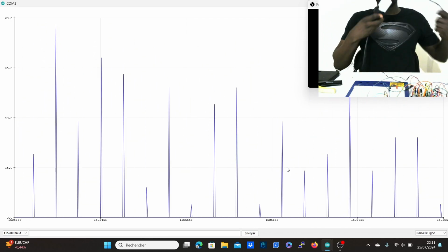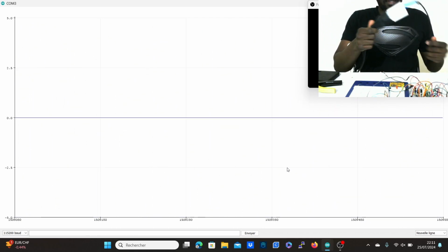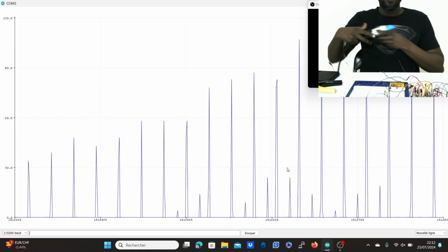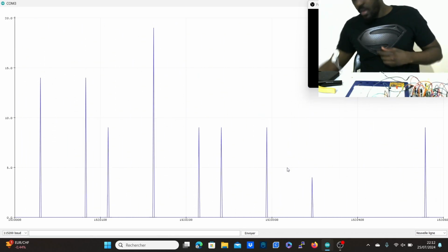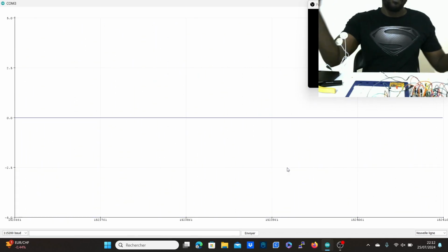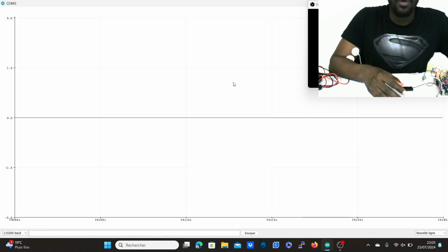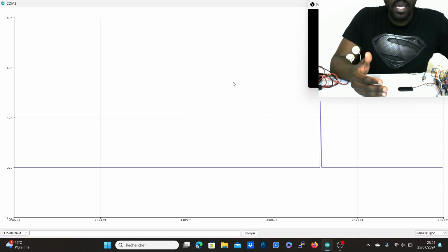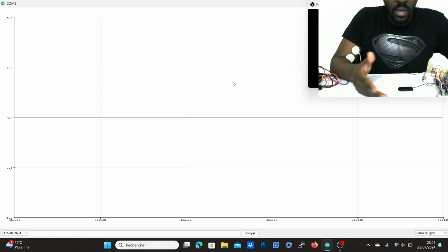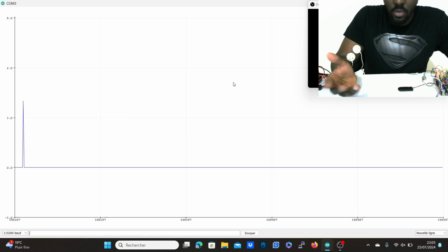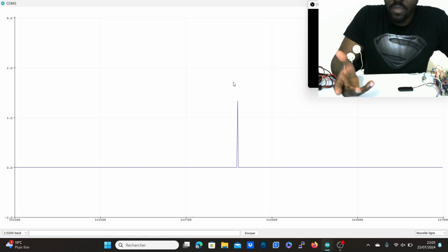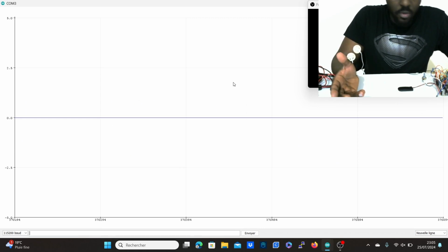So yeah, you can see it's not as bad as it used to be previously, but it's not working. When I was using the notch filter with my potentiometer, I amplified the initial gain by 11. So I multiplied the whole thing by 11, and the device was still not working. So that really shows you how strong of an attenuation we have with the notch filter.